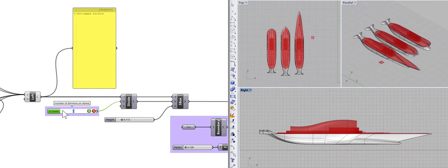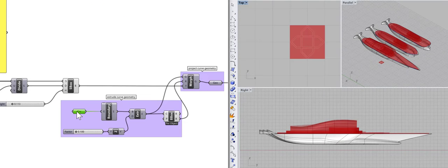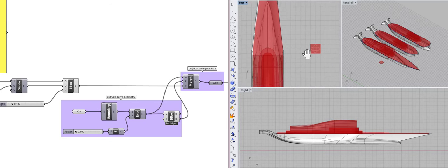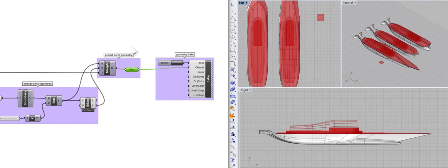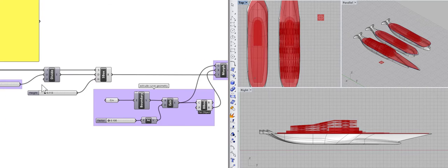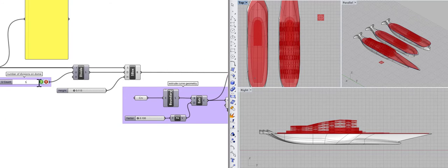Using Divide on the lofted surface allows for a number of divisions on the surface. S-box provides control of the height of the division projection. Each set of geometry may then be projected onto the divided surface. Results from DIVA's climate-based daylighting factor analysis exhibit a difference in daylighting between each grid of the geometric design. The larger the grid multiplier, the smaller the daylighting factor is.